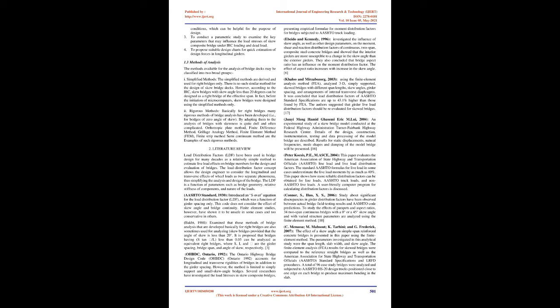High support reactions and shear forces developed close to obtuse corners, and low reactions and a chance of uplift reaction forces on the acute corners. 1.2 Objectives of proposed work.